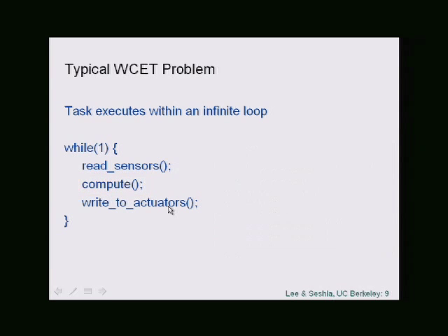So that's the typical form of an embedded system. And typically what we're interested in for timing analysis is just finding out how long this part takes. And this part typically is written very carefully. You have loops with finite bounds and no recursion, so there is no halting problem to deal with. You know the program will terminate.